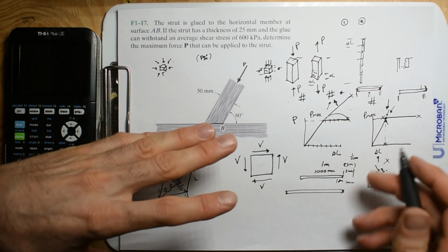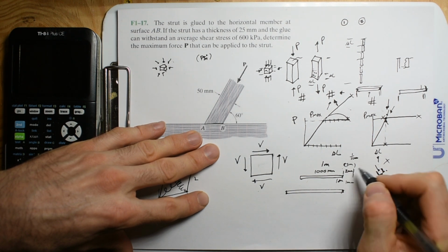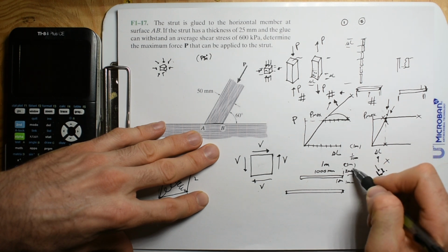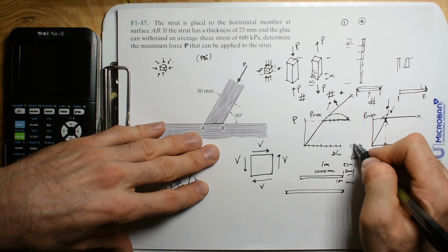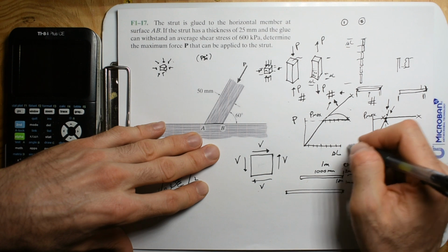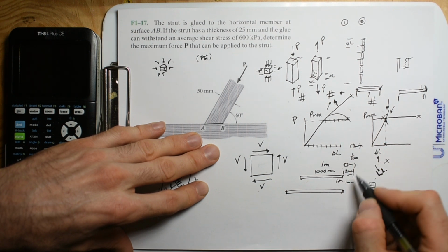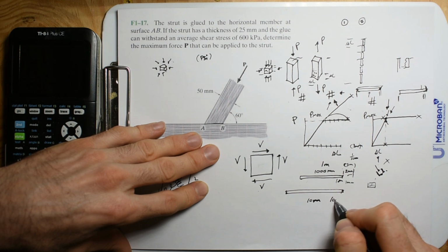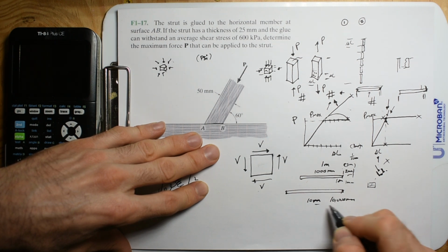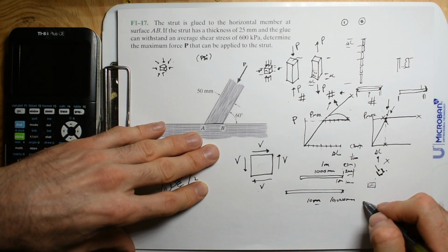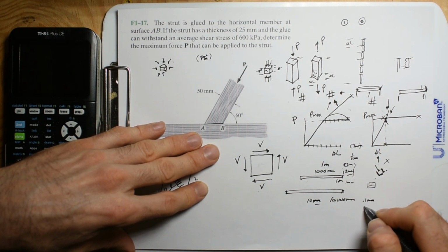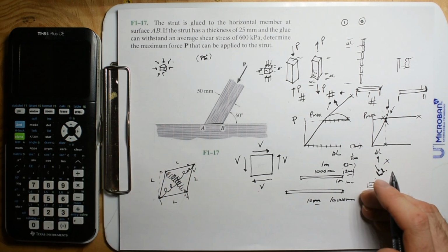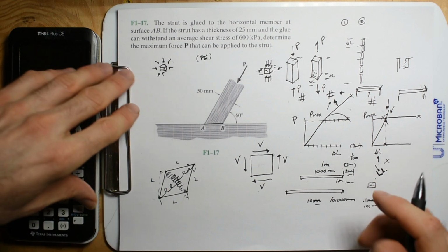Now when it comes to heat change, let's say you could have 2 millimeters. Maybe spec is saying that you can only lengthen it 1 millimeter, or just half. And then temperature fluctuations would be another order of magnitude lower. You know what I mean? For every 10 meters, or 10,000 millimeters, I don't know the number, but it's going to be at least 0.1 millimeter change in length, or 0.01. So it's either 10x lower or 100x lower due to temperature changes.